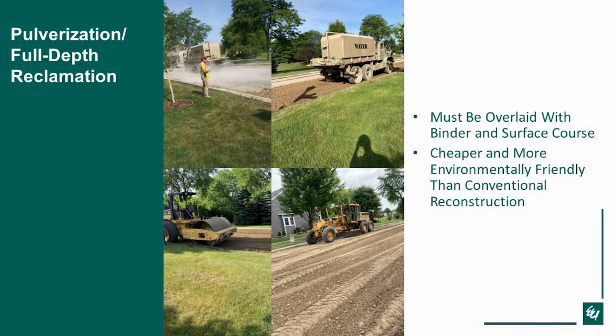And then what's in the bottom right would just be your traditional road grader grading out the new base. They'll roll and compact it, and then let it cure. One thing that you want to do with full depth reclamation with cement is to check whether or not you need to do micro cracking. If the full depth reclamation gets too strong, you come in and take a roller to micro crack the top, and that will prevent your base from acting as concrete, and will give it more flexibility so you don't have as many heaving issues.